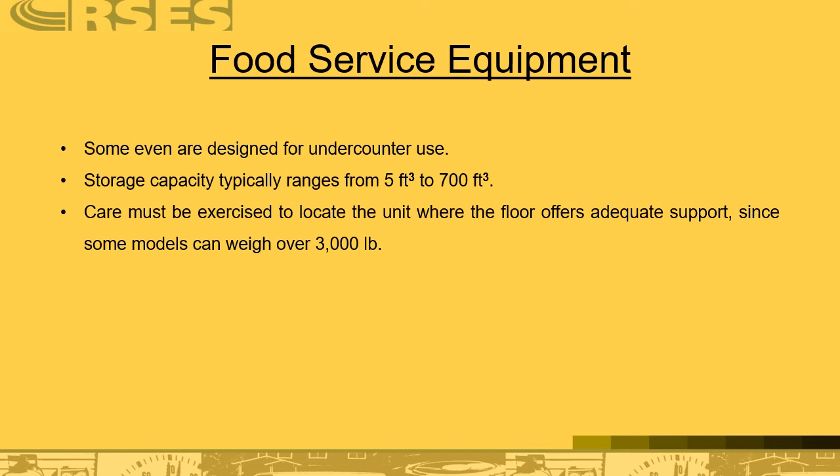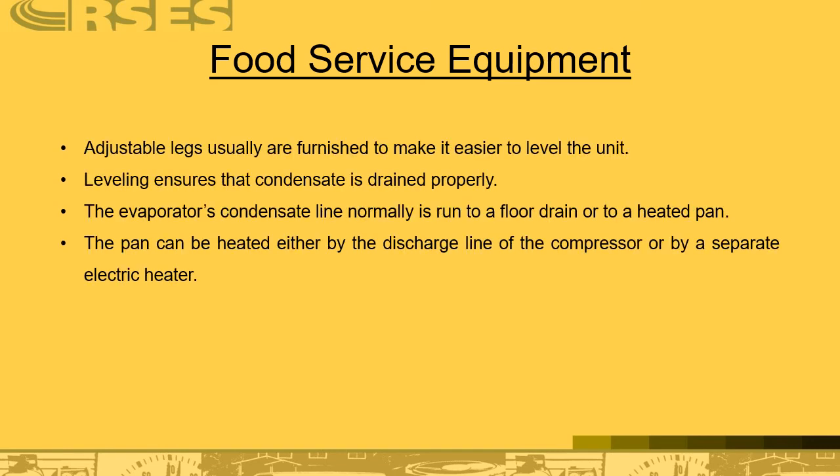Storage capacity is typically 5 cubic feet to 700 cubic feet. Care must be exercised in locating the unit where the floor offers adequate support, since the units can weigh over 3,000 pounds in some cases. Adjustable legs are usually furnished to make it easier to level the unit. Leveling ensures that the condensate is drained properly.